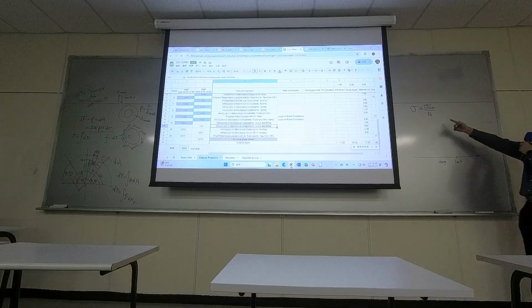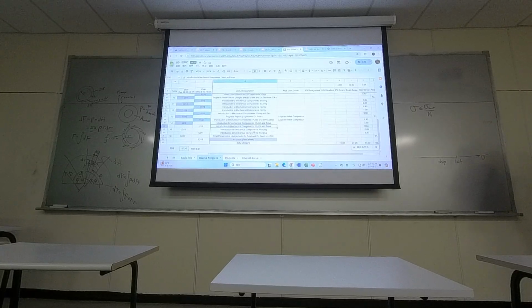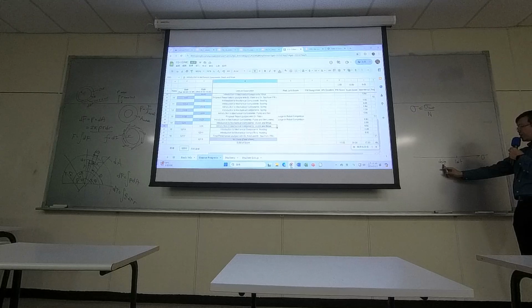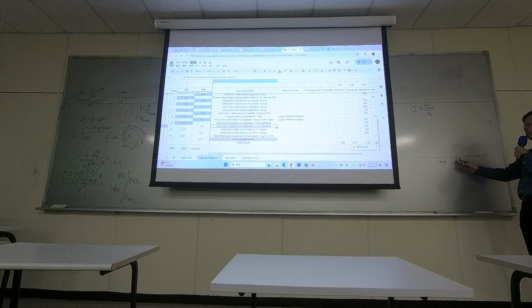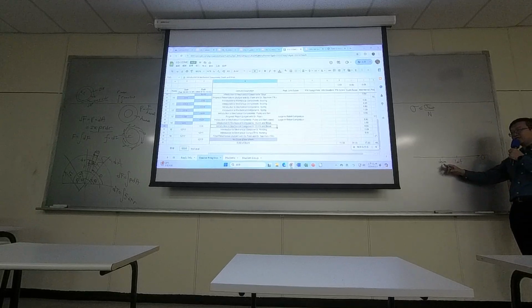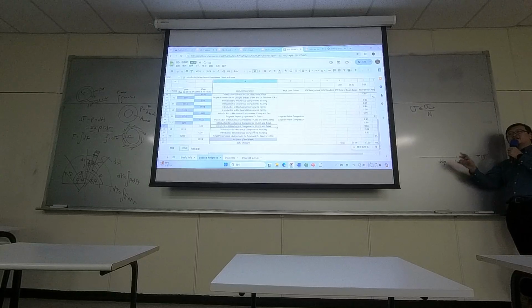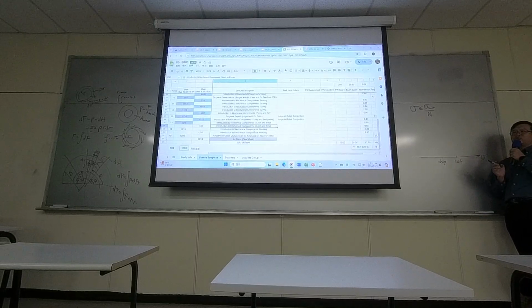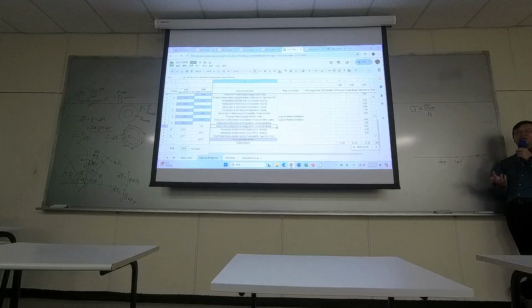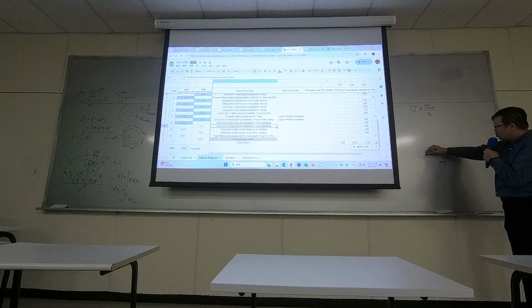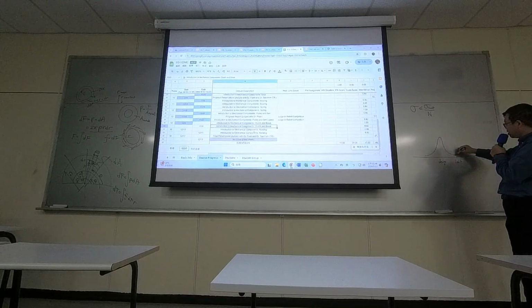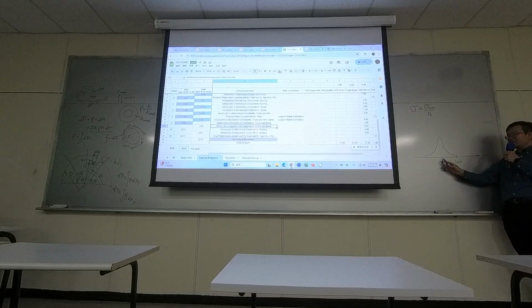So why do we design in this way? Why do we pick a design point somewhere that is a little far away from the limit? Because when we mass produce a design, it doesn't match what you are looking for all the time. There is tolerance. So in reality, whatever you desire to design will behave like a random distribution.